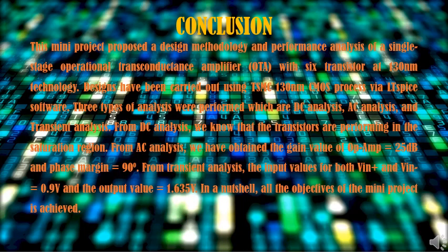For the conclusion, the mini project is designed as mentioned in the methodology with a single stage operational transconductance amplifier OTA with 6 transistors at 130 nanometer technology. So we carried out 3 types of analysis: DC analysis, AC analysis, and transient analysis.